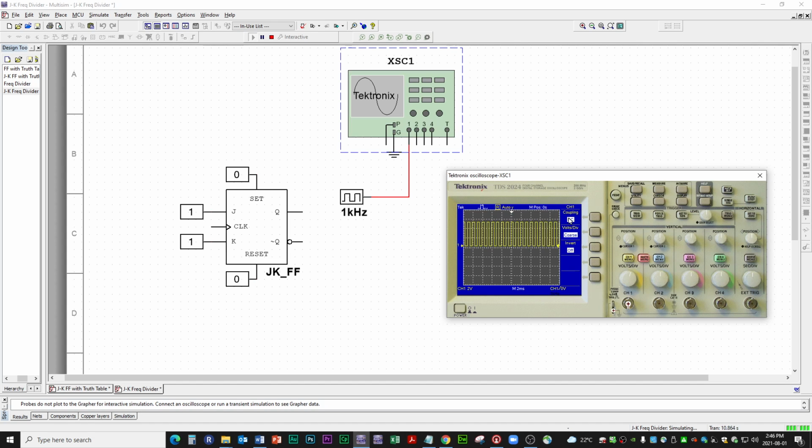Channel 1 menu, so we're DC coupled. If we go AC coupled, which means we're going to bypass the DC component, you see this signal goes high and low, and the high is above the 0 line and the low is below the 0 line. But this is the AC component displayed only. Sometimes we want to isolate the AC component, but not in this case. We're going to toggle the coupling.